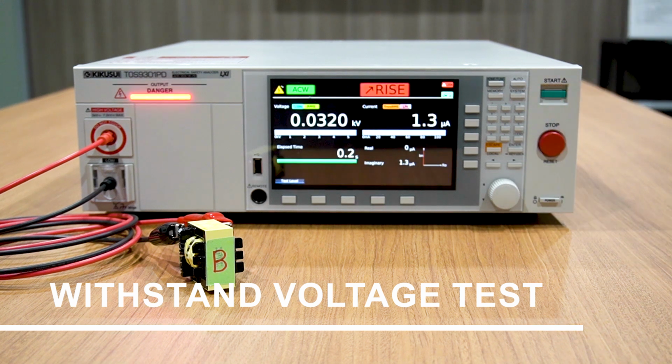Now, let's test sample B. In this case, as you can see, it also measures a current value of 23 to 24 microamps, resulting in a pass. In the withstand voltage test, it will be judged as a good product. However, in reality, as you can see, partial discharge is occurring and the product has the potential to become defective. But we were unable to detect this phenomenon only through the withstand voltage test.